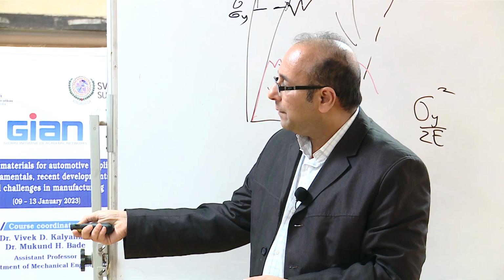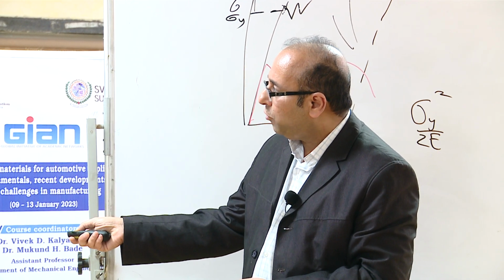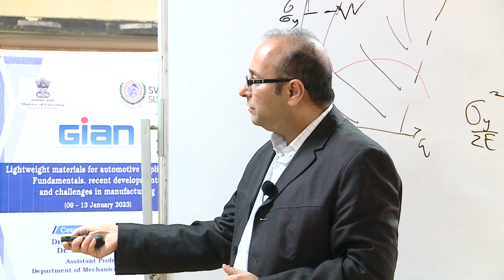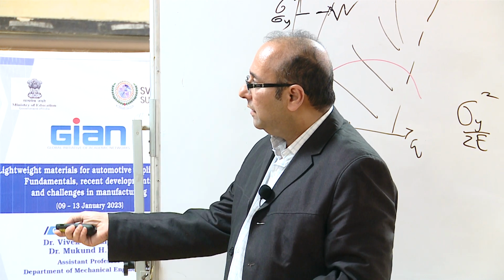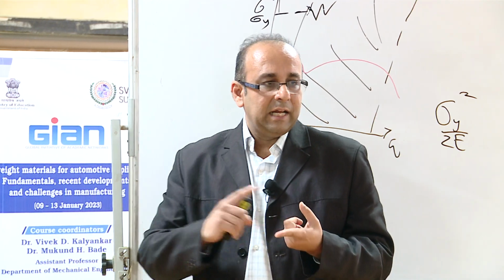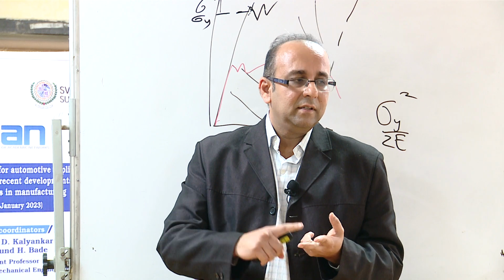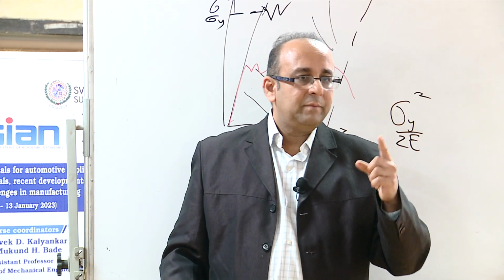So this was the earlier approach, all 4 parts of different thickness. Here's warm forming, fine, but still 4 toolings. Now what people do is make this complete side panel 1 single part, tailor welded blank, warm forming, soft zone, 20% mass saving, and better crashworthiness.